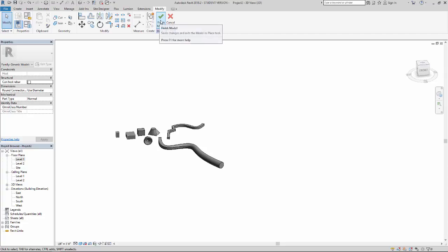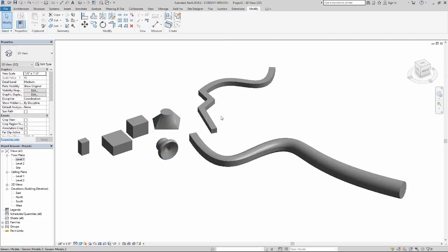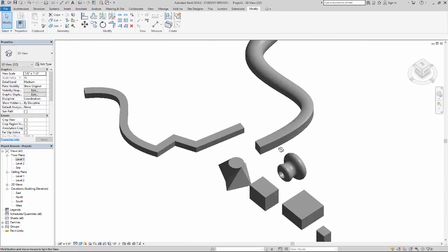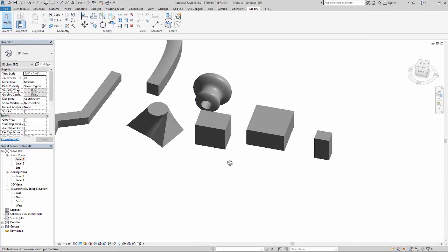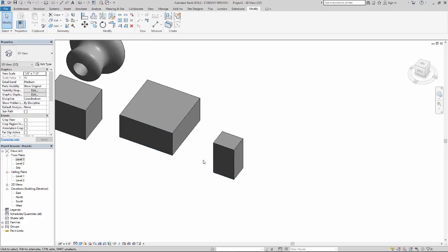So the next thing to look at as we're building these forms is expanding on that idea of a reference plane that we saw in our sweeps, because the reference planes can be really useful things to work with, and they help you model things in the exact location that you need them. So there are two key ways that I typically go about building reference planes. One is using an existing object, and the second is to actually create my own reference plane.